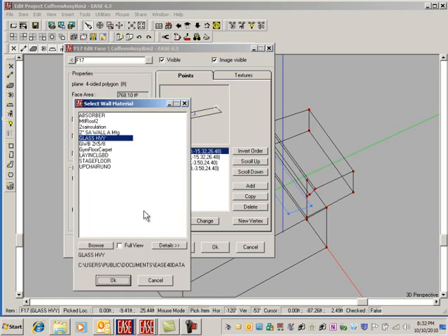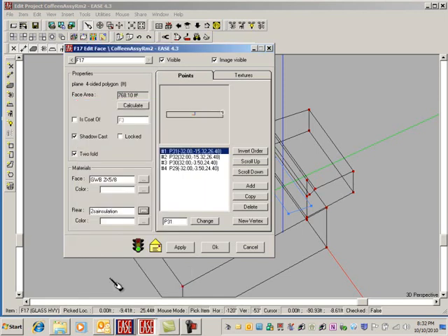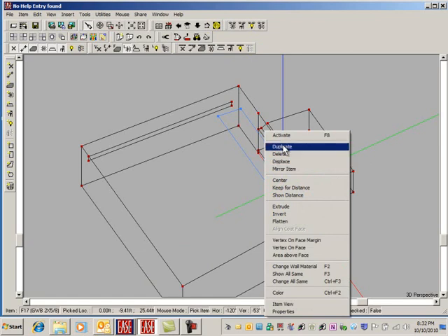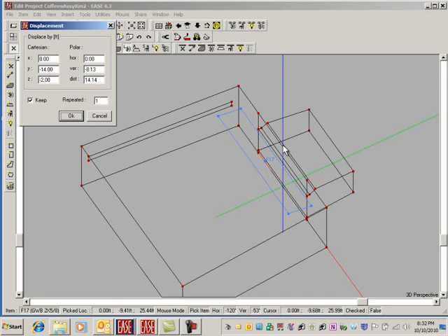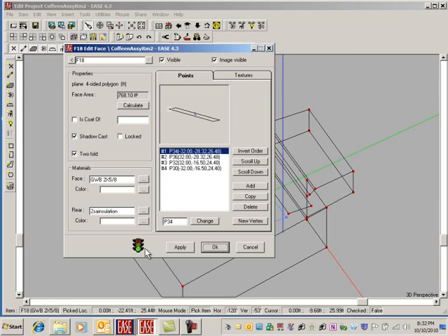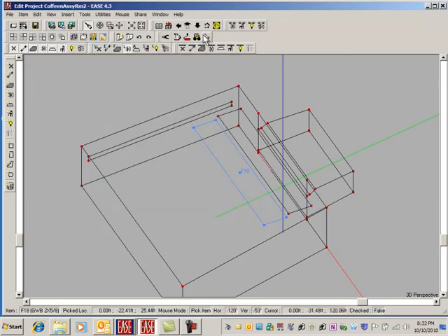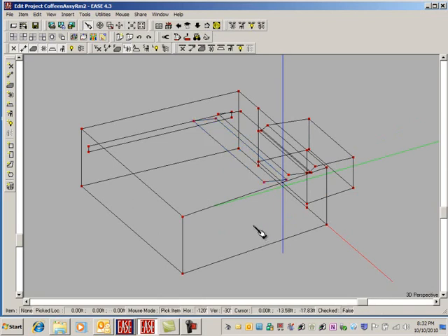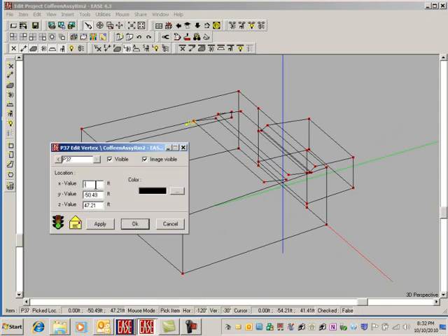Mirror this guy. Okay. Add a line. Same old thing here, like this. Extrude the line down 14 degrees and a distance of 12 feet. So we can say extrude. Over here, horizontal 0, vertical is, you notice that 9.98, that was 10 degrees, but because we're going from English to metric units and back again, it sometimes will change it just slightly, not to worry about. Minus 14 degrees, and a distance of 12 feet.